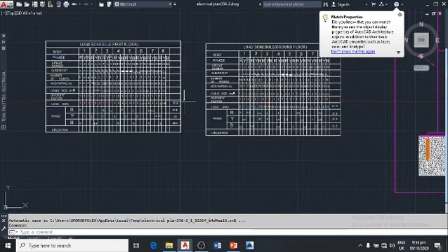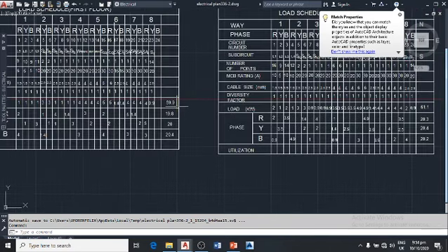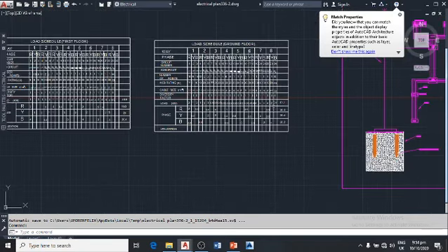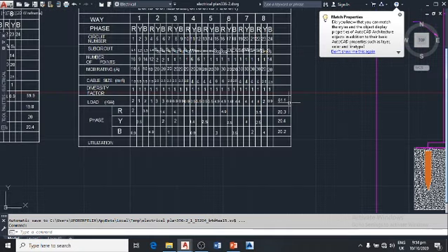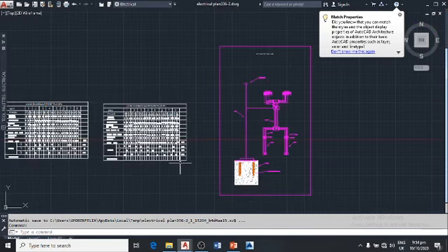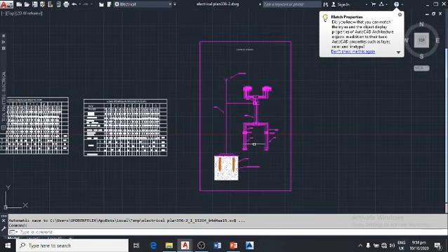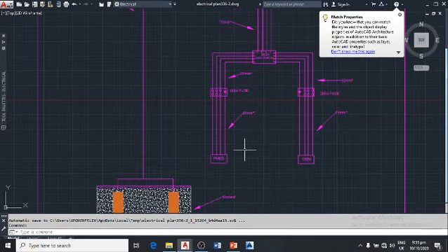So up there we have 58.9 kilowatts, and on the ground floor we have 61.1 kilowatts. So by the time you add the total load, I think we have 121 kilowatts of electricity in the building. So the building is rated about 121 kilowatts. Now 121 kilowatts is our total load,